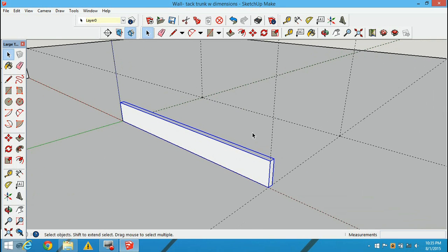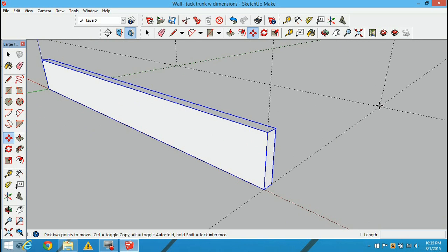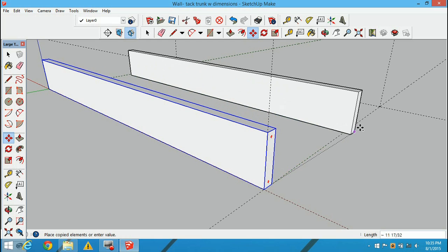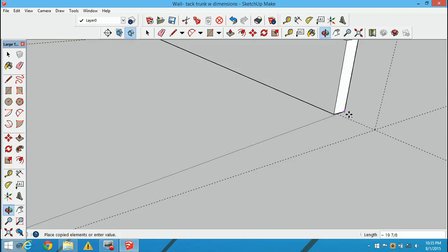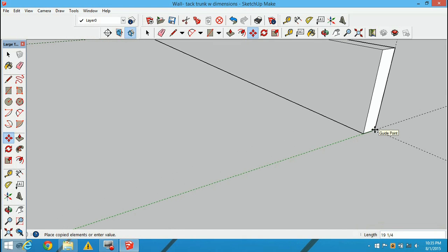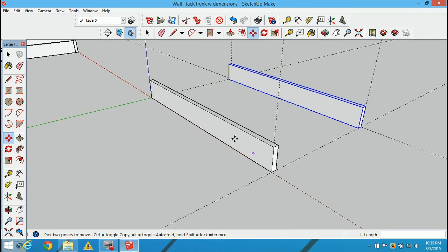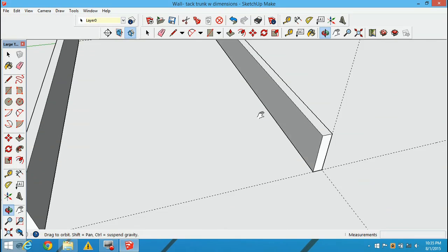Okay. Now, the copy tool, I'm going to grab this move tool, and we use that as copy as well. I'm going to grab this back corner. I'm going to move it right over here because it's going to be an identical piece on the back. So I click on there, click, it starts to move. Hit Control. Notice it duplicates it for me, and I can zoom in over there if I want. It snaps to that point I set up earlier. I click there. I didn't have to redraw anything. Okay. So now I just work on my side to do the same thing here.